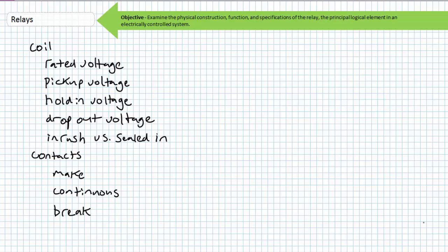The mechanical linkages, springs, and contacts internal to the relay must be periodically inspected for proper operation and signs of mechanical wear. Misalignment of the contact carrier, spring, lever, or foreign obstructions will prevent movement of the contacts. Silver alloys typically form the conductive contacts because oxides of these alloys are also conductive. Closure of the contacts should ideally be as rapid as possible.